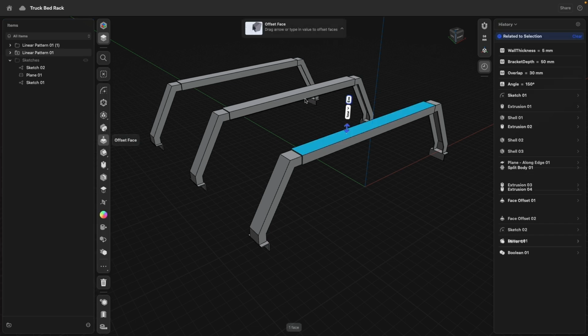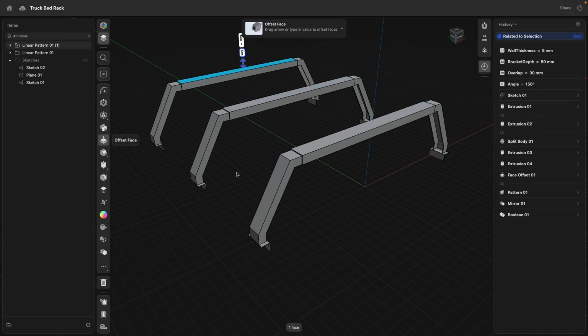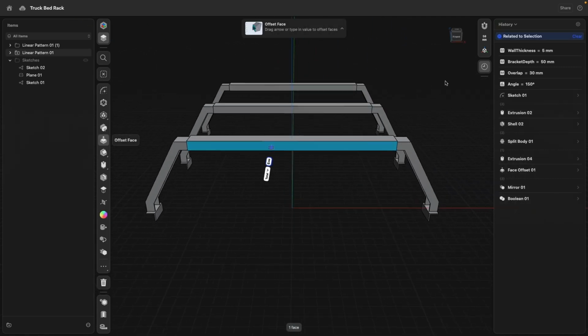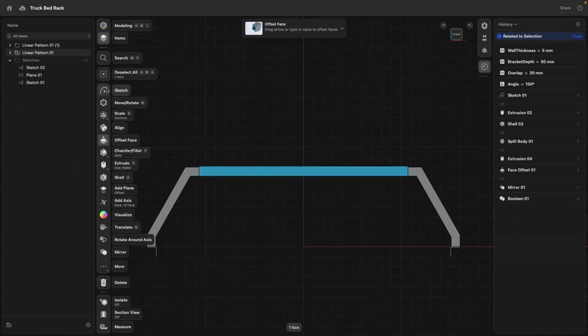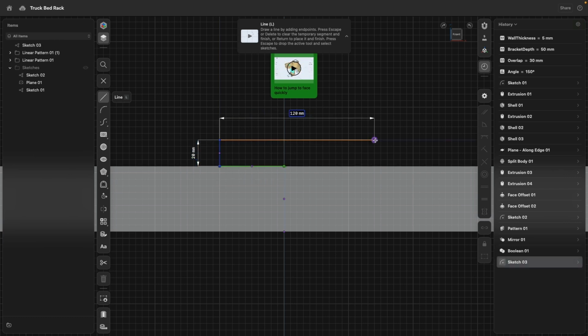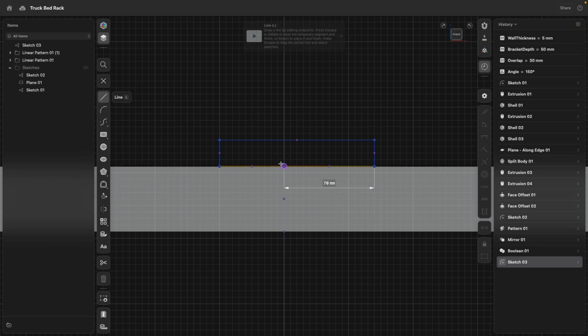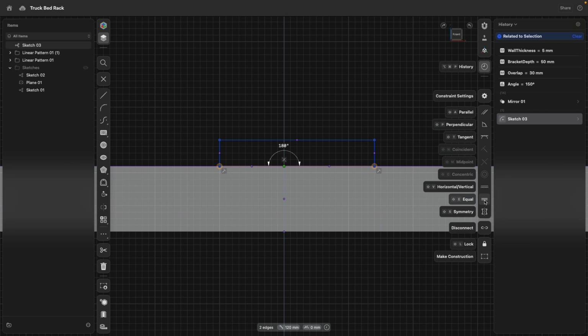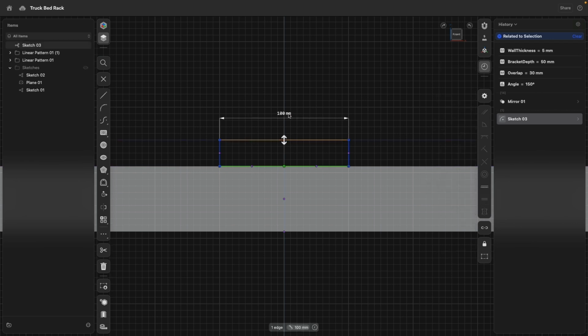I need to create a connection that goes over these 3 pieces, and the same then here. So I will go to this face and go to the front view, create a sketch. Here's my midpoint. That's beautiful. I draw a line straight to the left, up to the right, down, back to the edge and to the endpoint. Right click and drop the line tool. These, the first and last line will be equal constraint. Then I can say this rib should be 100 millimeters wide.